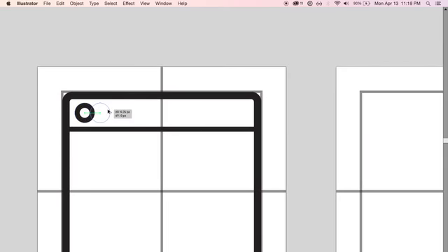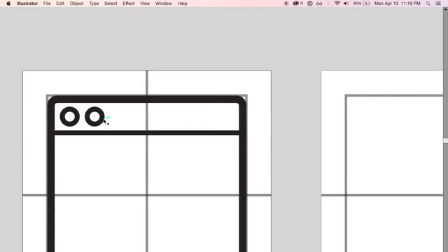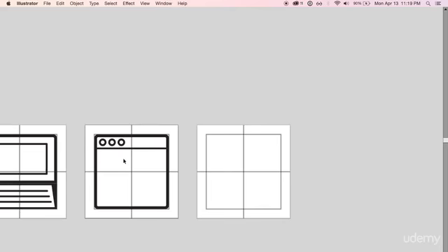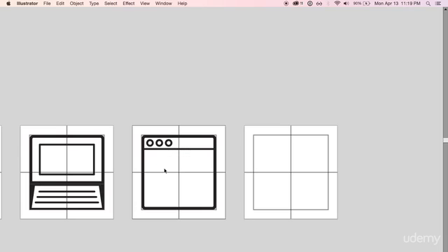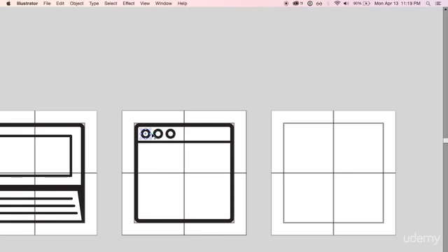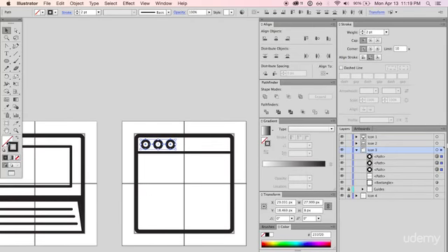We're going to do command, alt drag and hold shift to make sure that we have it far enough away, and we're going to do it again to duplicate. I'm setting these 10 pixels apart from each other. They're 8 pixels wide, 10 pixels apart, so it's got a 2 pixel padding, which is good. And then that looks consistent. These are also going to have fill in them, so I'm just going to go ahead and toggle that on right now.